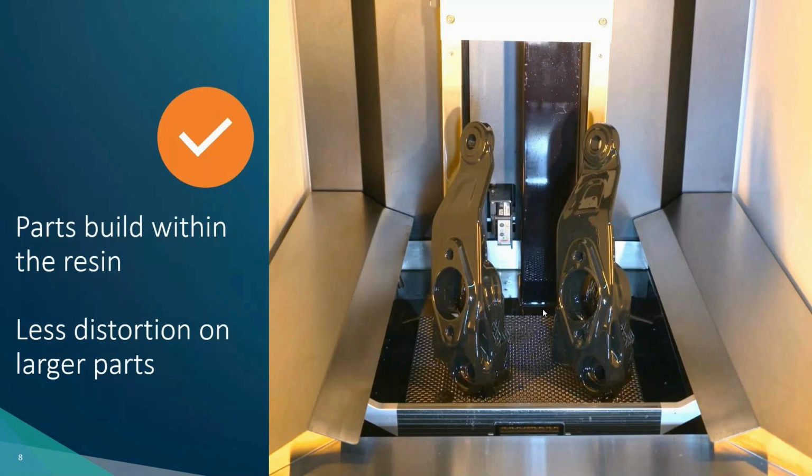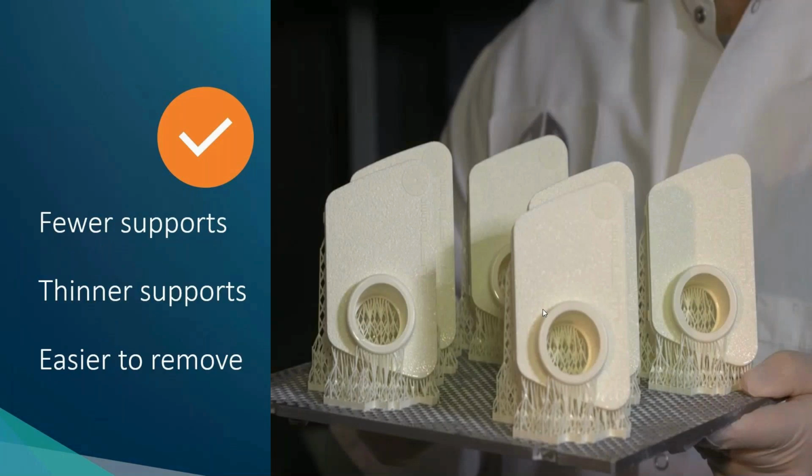One of the main advantages here is that you're getting less distortion on larger parts than you would if such parts or other parts were hanging upside down in the air. It also means that you have fewer supports and they can make do with thinner supports. So for example, these are parts that I was handling for the making of a PSLA 270 film. And I found that it was extremely easy to remove these particular parts from their support space. In most cases, I just had to do a single twist with my hand and the parts came off really cleanly with basically almost no supports attached whatsoever. So a very, very quick and easy process to remove those supports.